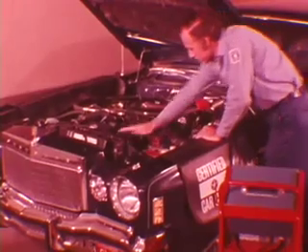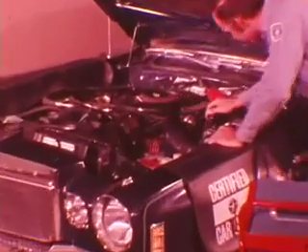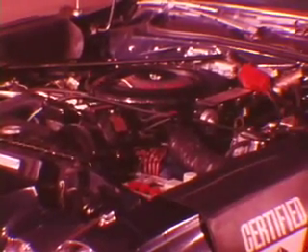Notice the additional spark advance caused by the start timer advance schedule. This will back off to basic timing in about 90 seconds. Run the engine up to operating temperature and kick off the fast idle. You can now finish the test of the carb coolant switches with the engine warm.